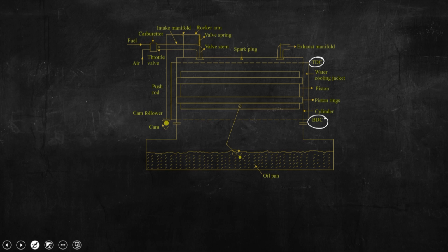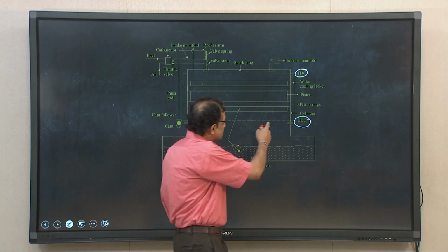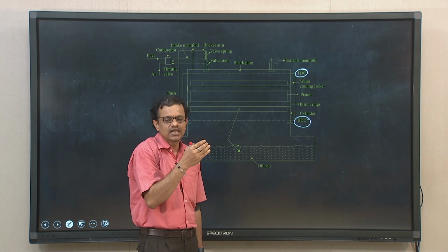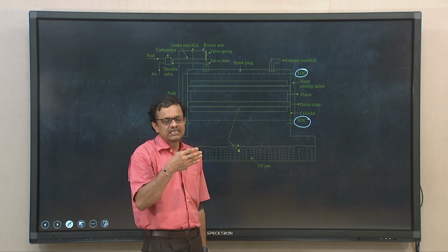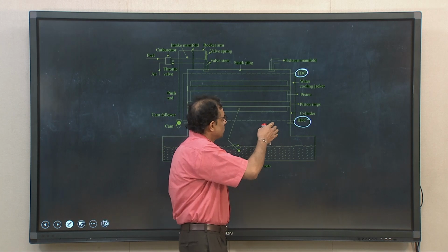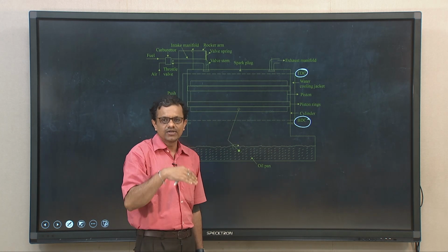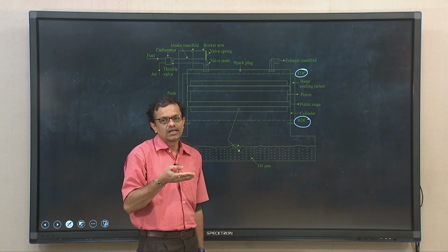So, the most important objective is to overcome the frictional losses, we need to supply lubricant, and since there is a relative motion between piston and the engine cylinder, we also need to take care of several other issues like wear and tear. So, all these are mechanical problems. So, lubricants are provided to minimize the frictional losses, to reduce the possibility of having wear and tear. Not only that, the lubricant also acts like a coolant.